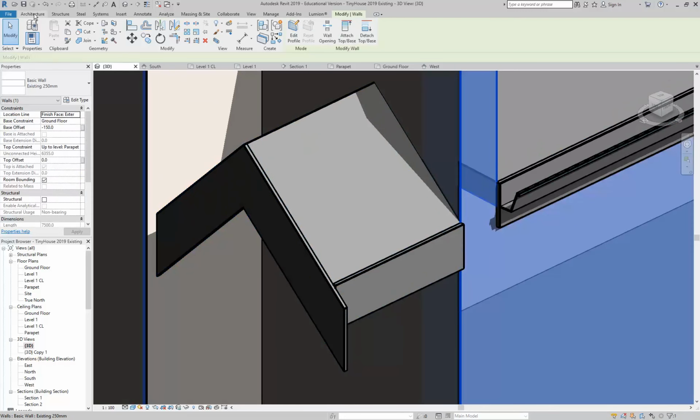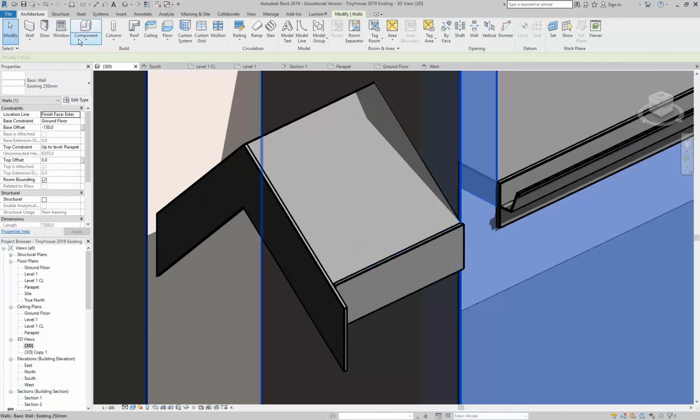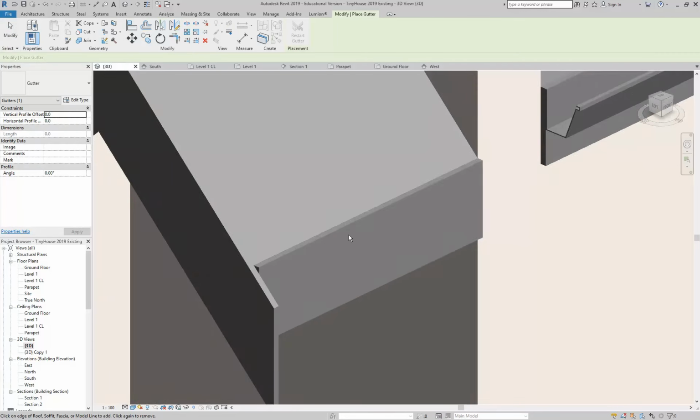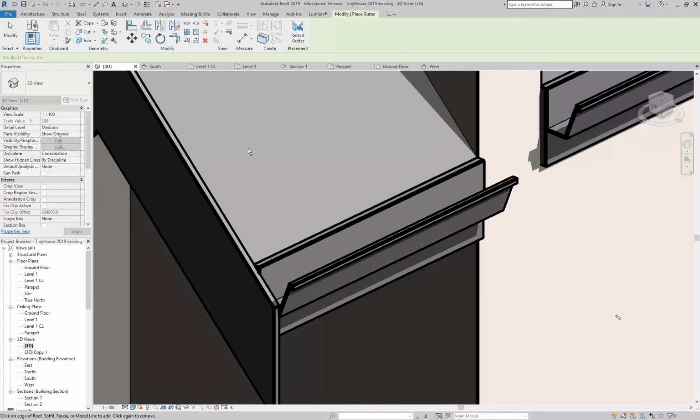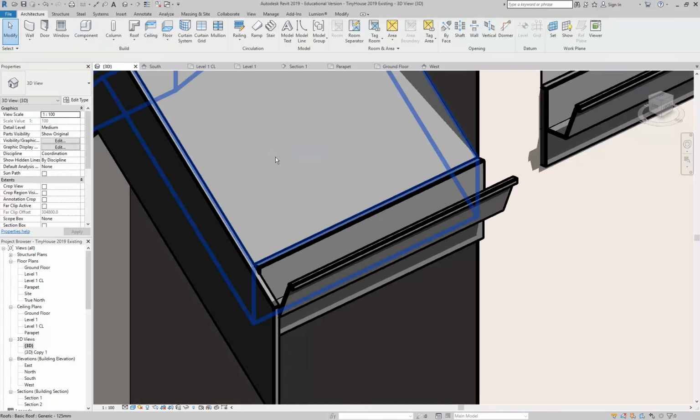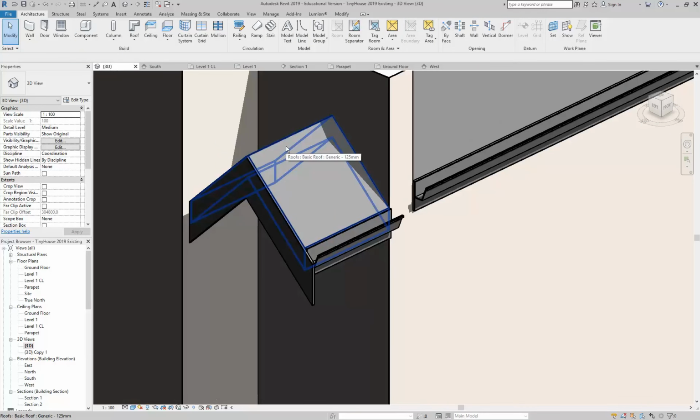And then if you want to, you could put a gutter on the side. I don't think you really need a gutter here, but you'd have to have a look at it. Traditionally, they wouldn't have put a gutter, but then if they've gone and done work to this over the years, they probably did add a gutter at some point. But have a look at those little roof forms. If you look around at things like dormers and other small roof forms like this, you'll see traditionally the standard detail is not to have a gutter.